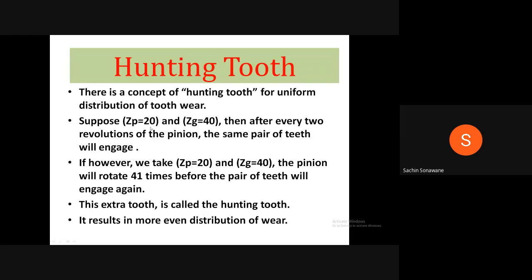Therefore, if the same pair of teeth will engage, what will happen? After some time, not suddenly, maybe after 2 to 3 years, wear and tear of the teeth will take place because the same teeth are coming in contact with each other. Therefore, to avoid that wear and tear, or so that the reliability of the gear drive is more, what we have to do? We have to provide one extra tooth.